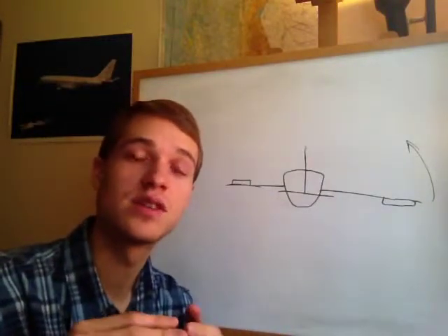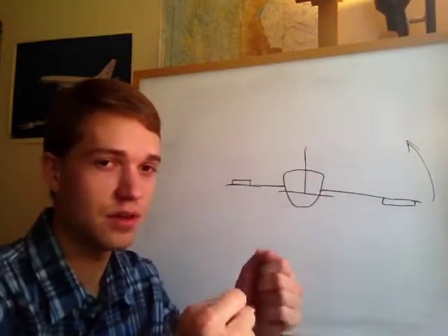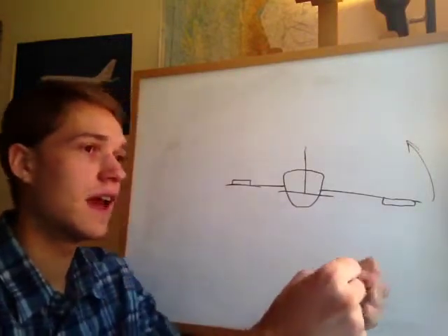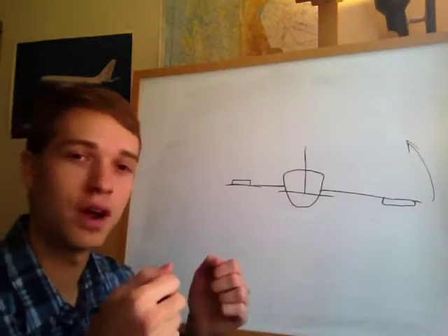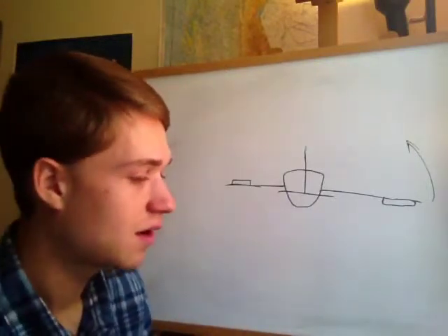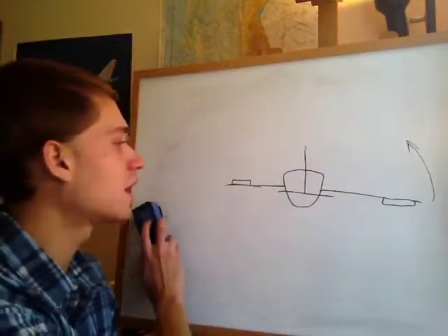And as the airplane gets slower and slower, the controls get sloppier and sloppier, and you're going to feel that you're going to have to move them a lot more in order to get enough pressure on the controls. So that's how airplane controls feel when you're flying.